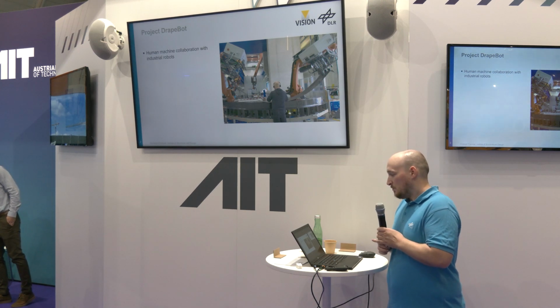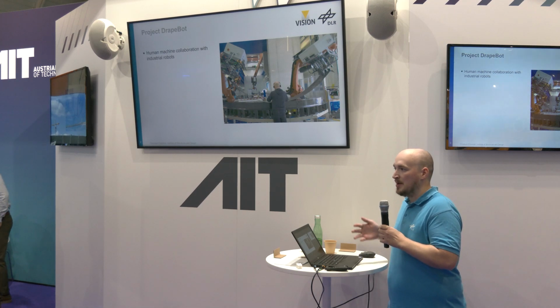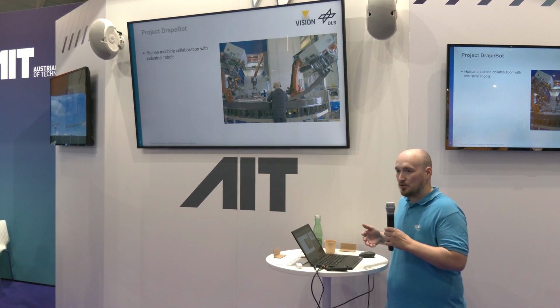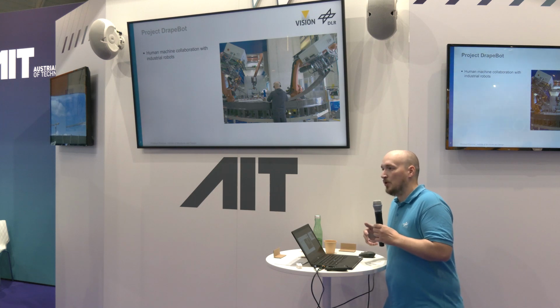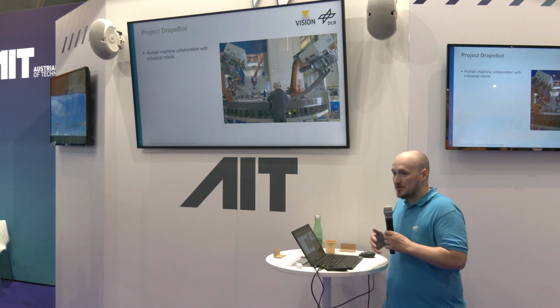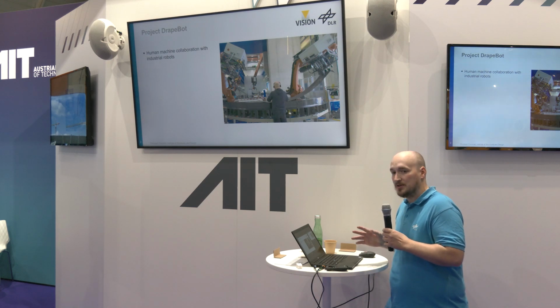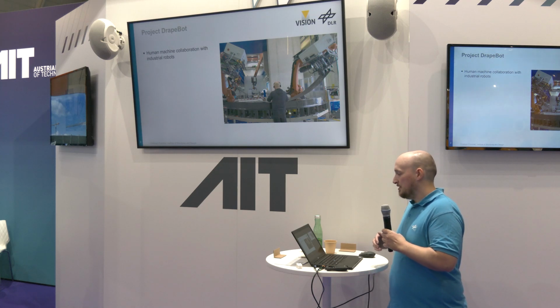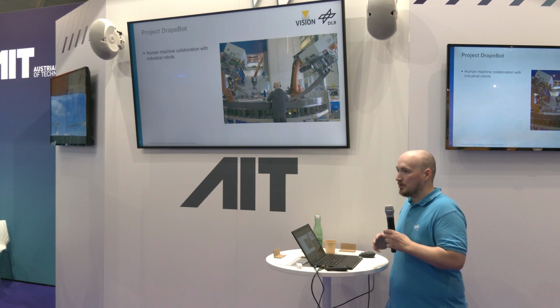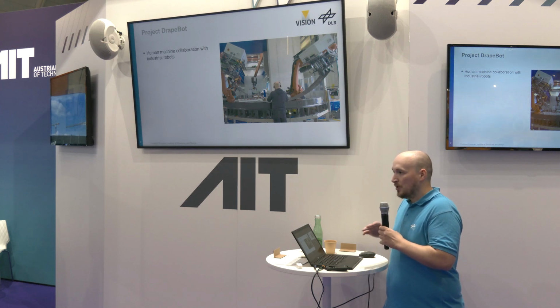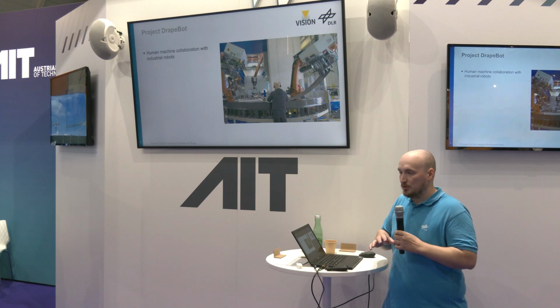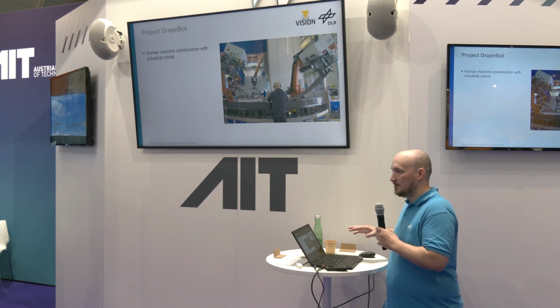And what we do at our institute, we build airplane parts. We try to automate the manufacturing processes for fiber reinforcement parts. Since it's an additive process, we stack layers of fabrics, in our case carbon fibers, in other cases glass fibers or other materials. And one of the first process steps in that process chain is the preforming, where you drape the fabrics from the two-dimensional state into the three-dimensional state, how it should be done in your mold.